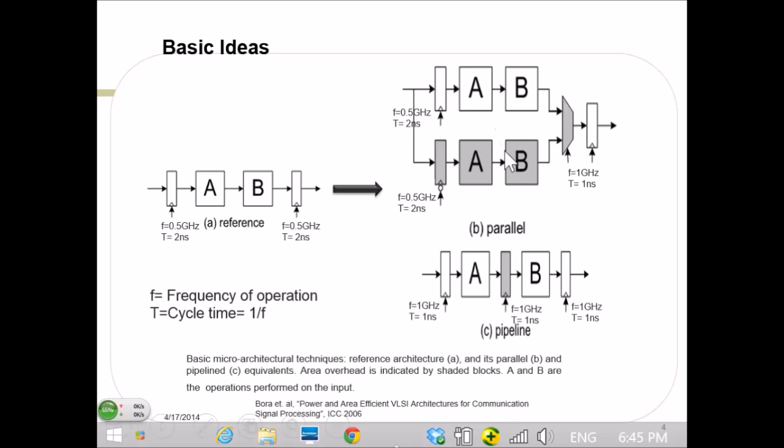If you are worried about the power consumption, the choice people make is: rather than pushing the frequency, let me put two parallel paths. That basically helps with the power. And if I'm concerned more about the area, I would say I can do 1 gigahertz easily at 28 nanometer, so let me push until 1 gigahertz. But beyond 1 gigahertz, I probably don't push any further in 28 nanometer for any ASIC. Then I would go for parallelization. So it's usually a trade-off.